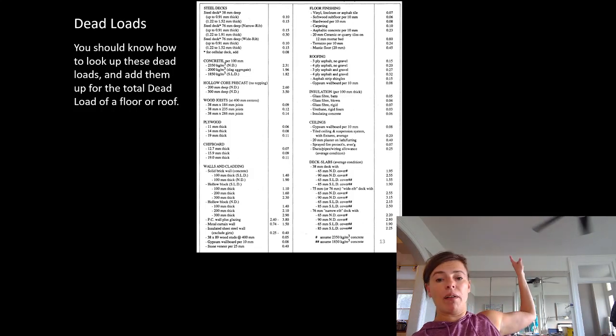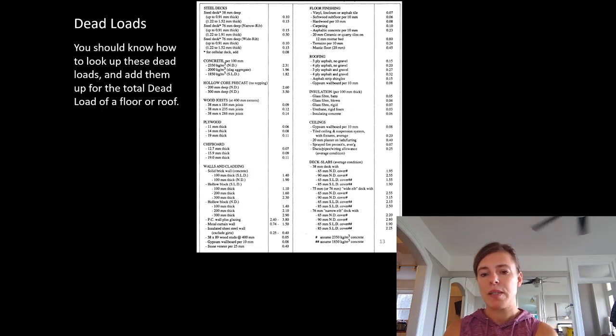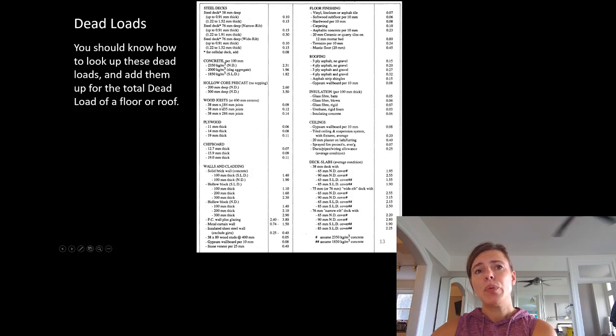You can actually see it here on the underside of my ceiling. We've got some, actually this might be lath and plaster, whole other thing, but often we use gypsum wallboard as another nomenclature for drywall. We have plywood, we have wood joists here. So these are calling up 2x8s, 2x10s, and 2x12s at 16 inches on center, or 400 millimeters on center.